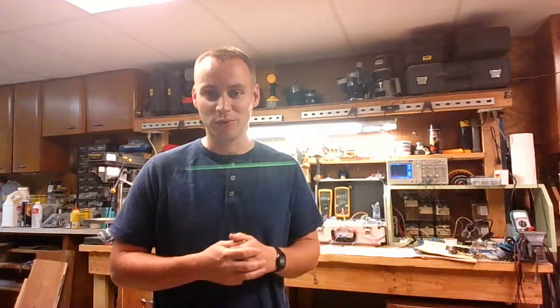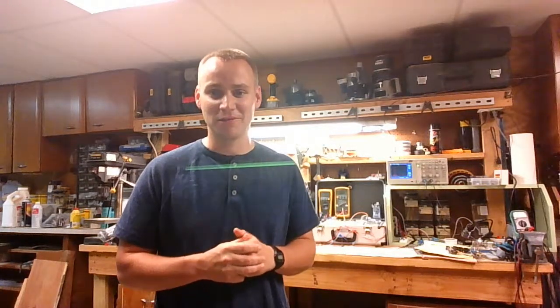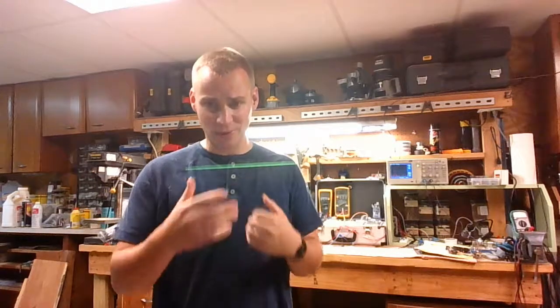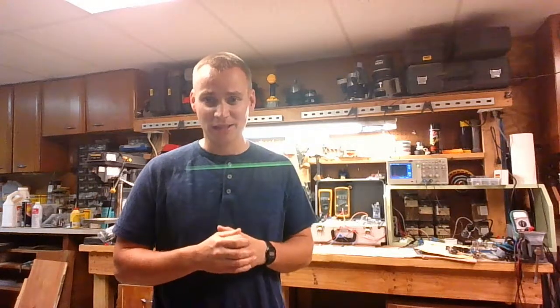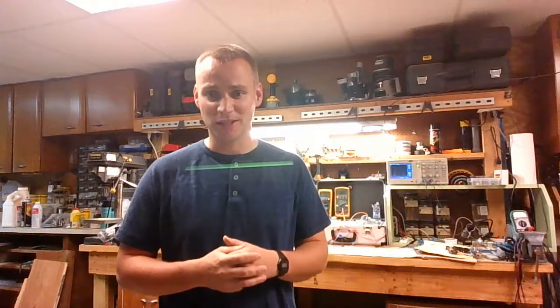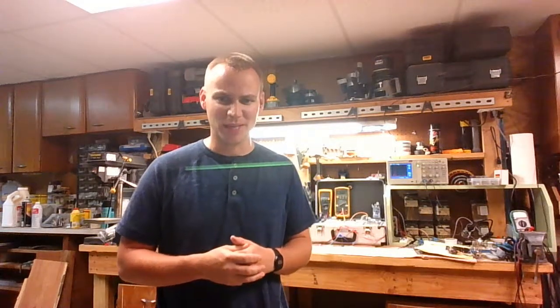One of the ways we want to accomplish this is to run an FFT on a current sample. Once the FFT is complete, we intend on being able to identify frequencies with higher amplitudes when certain major appliances are on. We are not quite sure how we want to accomplish this yet. At this point, we're still researching and experimenting with different microprocessors to decide what will work best.